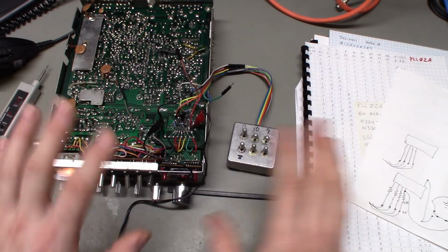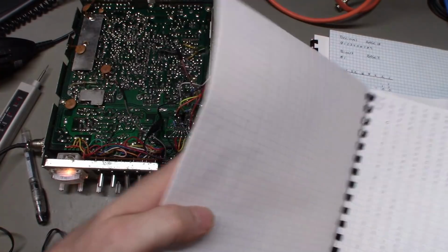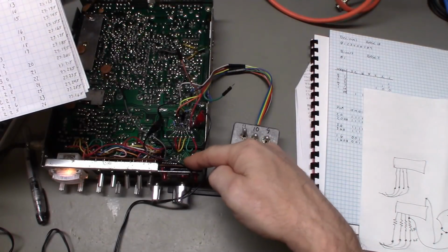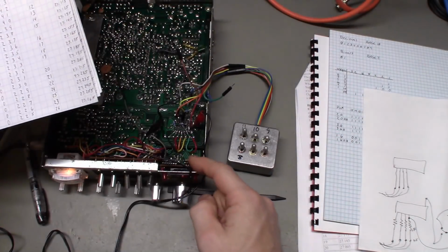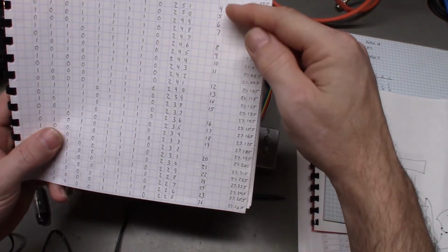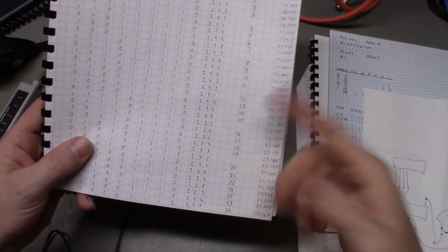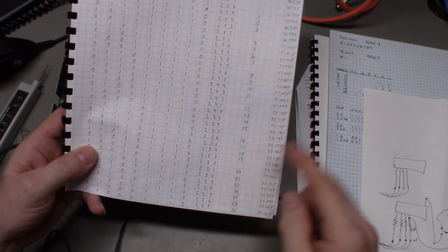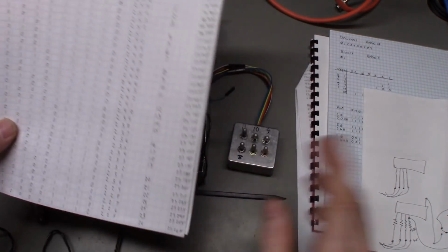The things that will easily get you when you start doing this kind of stuff: don't forget to skip channels when you're trying to make up a channel chart, or you're trying to get banks of channels. Don't forget the channel selector switch contacts in there are just fixed. The channel selector switch is what it is. There are actually 45 basically slots, but only 40 positions, because it skips the binary encode for these 5 channels that are used for other things. Nowadays I think it's mainly remote control cars and whatnot. But don't forget those. If you're working specifically on a PLL02A, don't forget the code counting backwards, the pins backward. All these things are backwards.